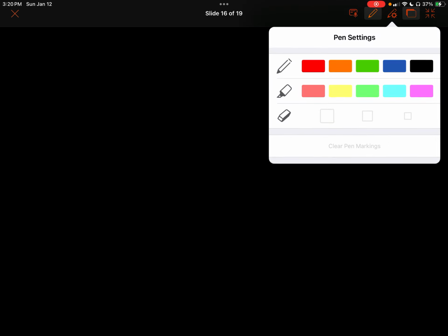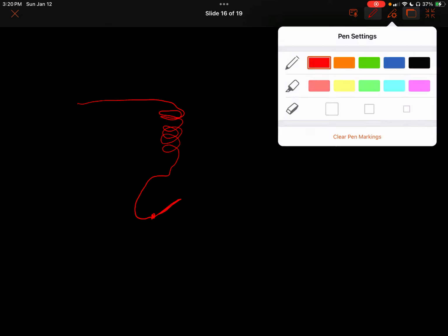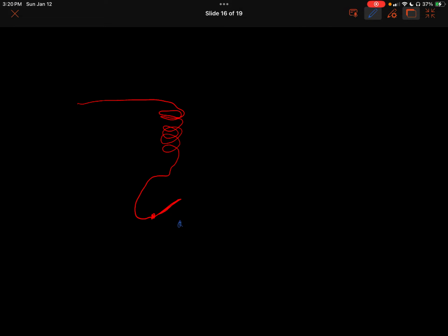Let's go back here. So if it goes into a pop state, here's our coil, and now our switch is open. The reason it opened is because the current got too high. Here's the output side. Our current had gotten too high, and that caused this iron core to get pushed up by electromagnetism, and it pulled the switch open.